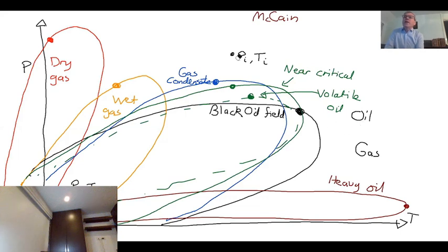Okay. So you have an oil and a gas. And the gas can dissolve in the oil. So we have different amounts of gas that can be in the oil. So what we do is we describe our hydrocarbon mixture as a liquid phase, that's oil, and that oil will have properties that will be a function of temperature. And then as a function of temperature and pressure, there will be a gas, and the gas is assumed to have constant composition, and a certain amount of gas can dissolve in the oil.